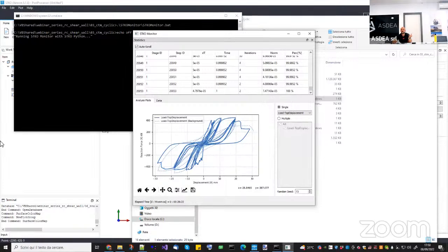And with this equivalent scalar, they govern everything. That's why they behave as a very homogeneous and isotropic material, because at the end of the day you have just one scalar measure. Now, in our case, it is a two-parameter model. You have two scalar measures, one for tension and one for compression, but you do not distinguish different directions.